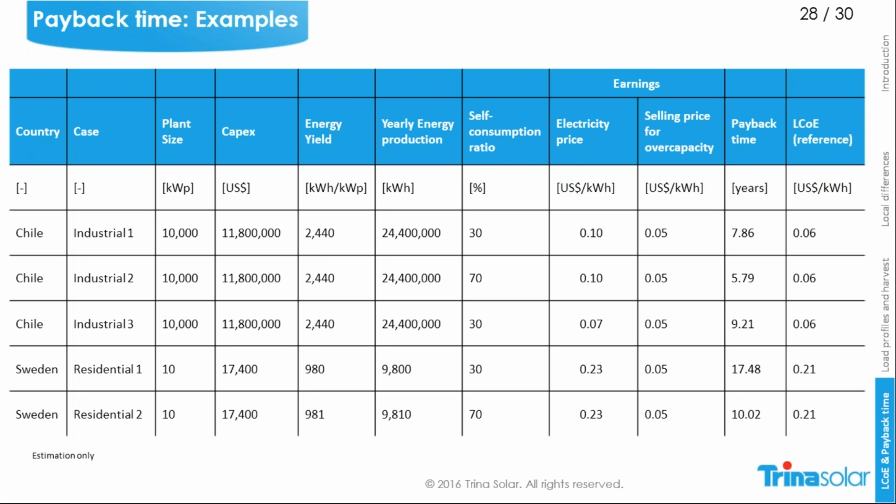There you can see that for sure the location makes a difference, because the system price is for sure different as well, depending on, for example, material costs and labor costs. But I can also see that the energy yield, which is approximately 2.5 times more in Kalmar than in Stockholm, impacts your payback time, as well as, for example, the self-consumption rate or how your system design looks.